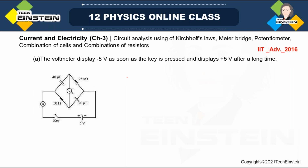So look, when the key is pressed, immediately after that, see the voltmeter, the first option says the voltmeter displays -5 volt as soon as the key is pressed, and it shows +5 volt after a long time. So how to solve this? Yesterday we had seen how to solve it. See, we can use Kirchhoff's voltage law, and before that we need to know some characteristics of a capacitor.